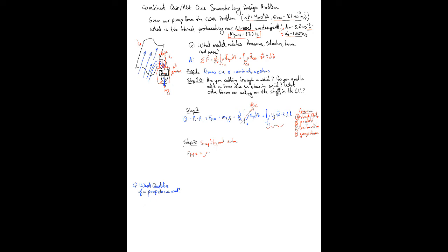Remember, this first one is for our Vy, and our second one is our W dot n hat. It's also a negative V1 because it's entering perpendicular to our control volume, so it's negative. And then we have an A1. And so this ends up being equal to rho V1 squared A1. And that's our first entrance.